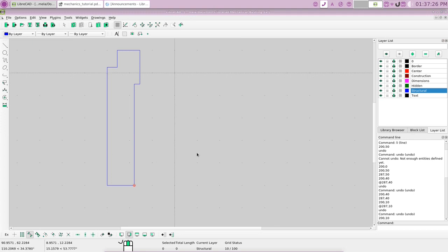Okay, so what we can do is switch over to our construction layer. Let's make a line, snap on end, horizontal, 8 units. Here I have 12, I only want 8. Snap on end, and there you go. Now up top here, from this point, we want half of 25, which is 12.5 for a radius.